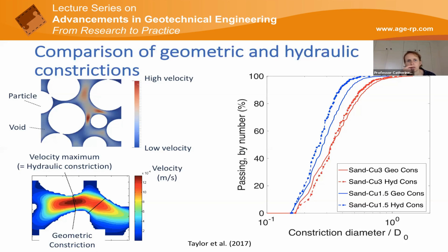Okay, let's take the next one. This question comes from Professor B. Amir from Jammu and Kashmir, India. He mentioned that particle size distribution is indeed a critical property when we look at dams, and what would you consider as an appropriate methodology for determination of PSD of dam granular material? You can use sieving, it's quite cheap.